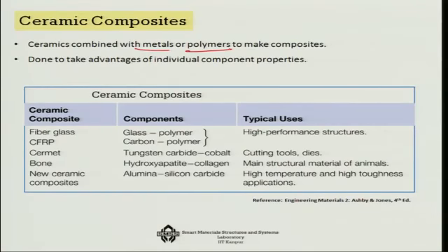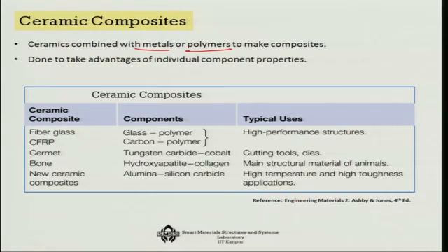For example, as fibers, ceramics have quite high modulus of elasticity, so you can take advantage of it. And also you know that on a macro scale ceramics are generally very brittle, but if you draw them in the fiber form, then they are not so brittle, because they are less susceptible to cracks, and hence they are very good reinforcement components in composites.